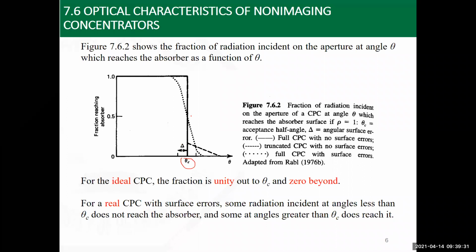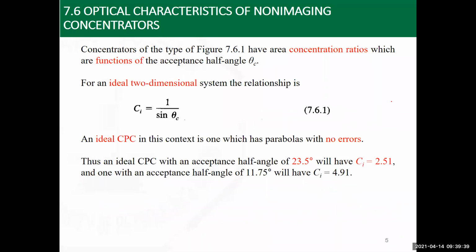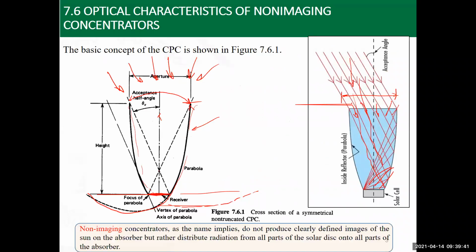And in some cases, just for the sake of optimizing the manufacturing of this unit, they would ask: do we really require the whole length of the unit like this? Do we have to go for all that length? Actually, most of the energy, maybe 90% or more, can be received if you are talking about a shorter CPC. They call it a truncated CPC.